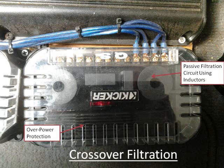This network is designed specifically for the driver combinations that I have used in my car, and sets thresholds exactly for the filters to get the most out of these speakers. In addition, if the speakers were overdriven by some enthusiastic do-it-yourselfer, the network has a light bulb to burn off excess power which could damage the speakers.